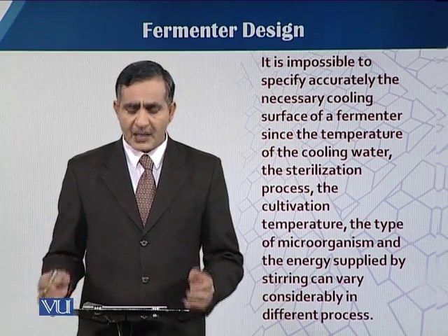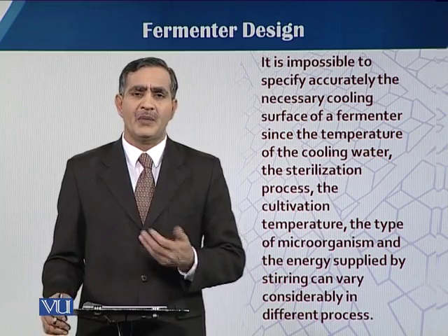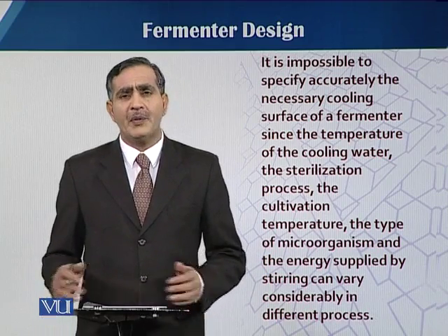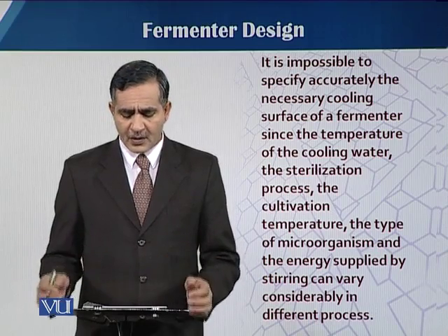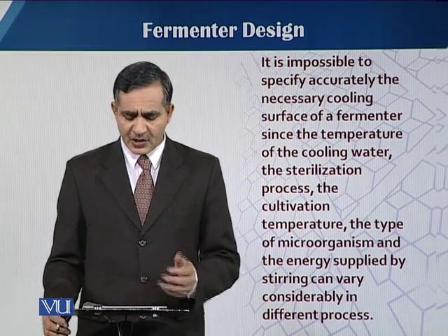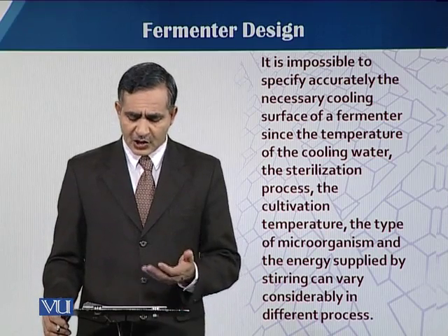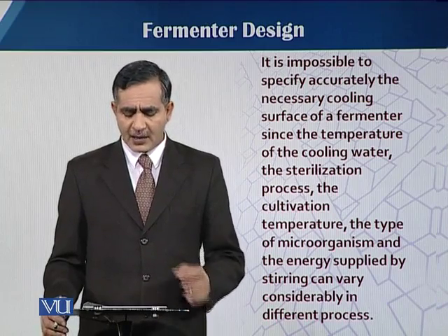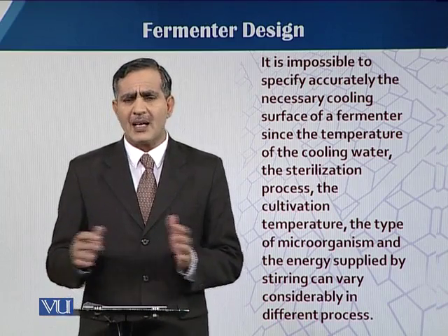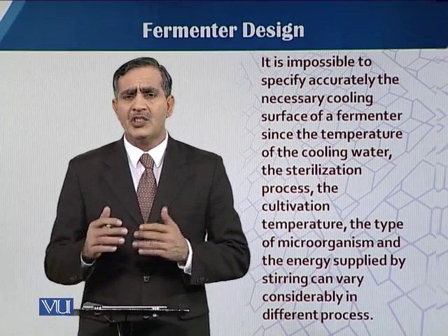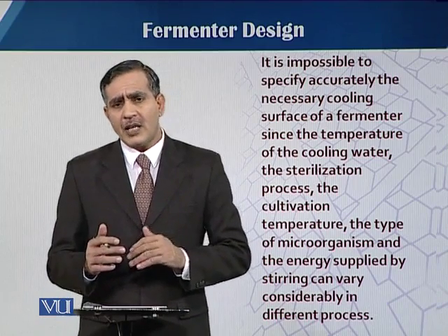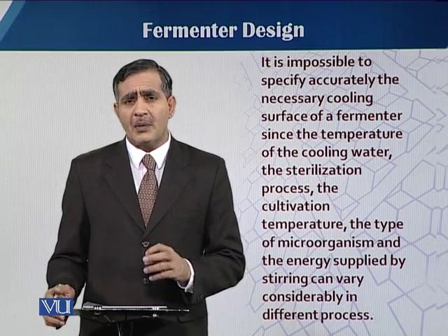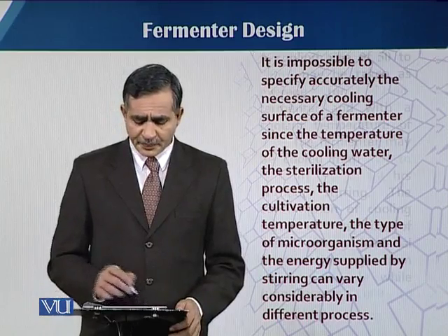That's why it is very difficult to calculate U. Sometimes we have to add to the surface of the fermenter, since the temperature of the cooling water, the sterilization process, the cultivation temperature, the type of microorganism and the energy supplied by stirring are different factors which change from time to time. That's why it is very difficult to determine using this equation.